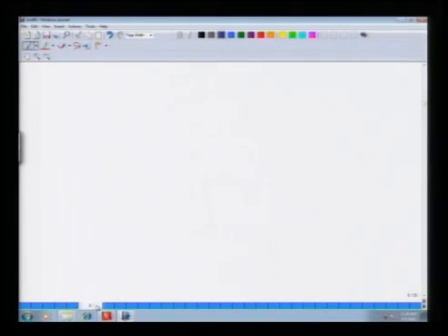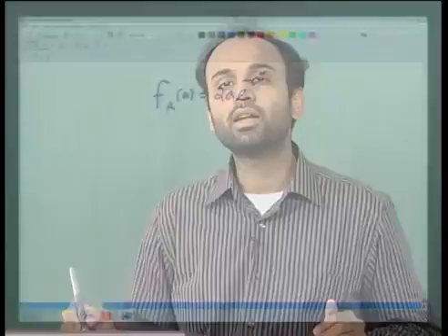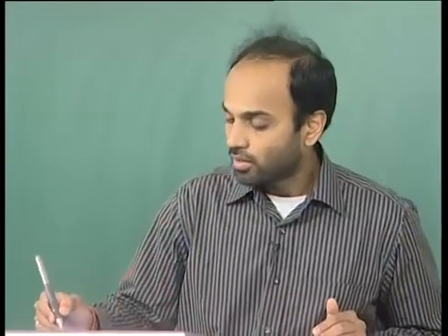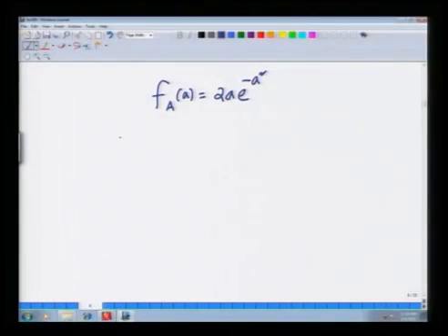All right. Now, we know that the probability distribution of A, the fading coefficient, is the Rayleigh fading distribution, which is given as 2A e power minus a square. We saw this in earlier lectures, that the probability density function of A is nothing but the Rayleigh fading density, which is 2A e power minus a square. Hence, we can say that the probability of a deep fade, remember A is a random quantity, so we have to talk in terms of probabilities.